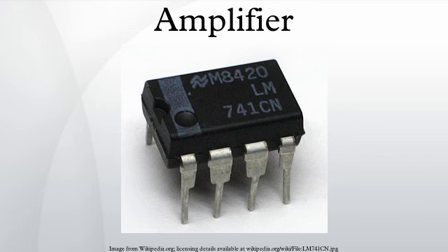Classes G and H. There are a variety of amplifier designs that enhance Class AB output stages with more efficient techniques to achieve greater efficiencies with low distortion. These designs are common in large audio amplifiers since the heat sinks and power transformers would be prohibitively large without the efficiency increases. The terms Class G and Class H are used interchangeably to refer to different designs, varying in definition from one manufacturer or paper to another.